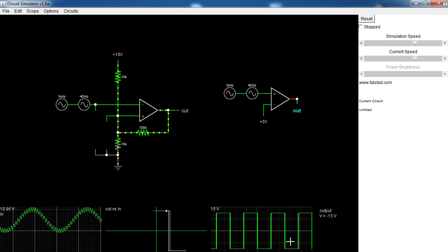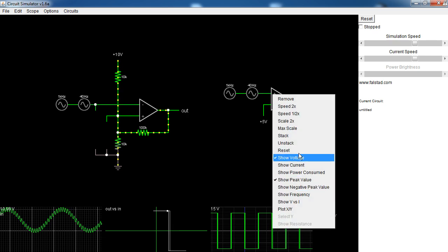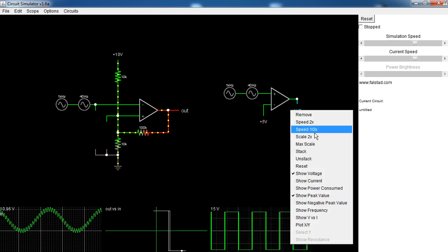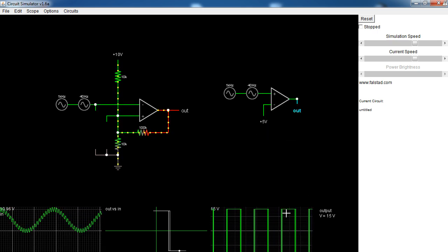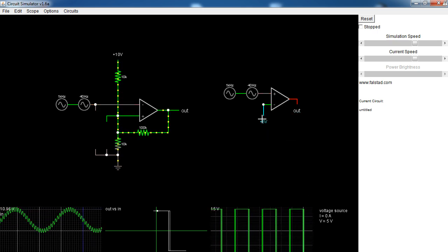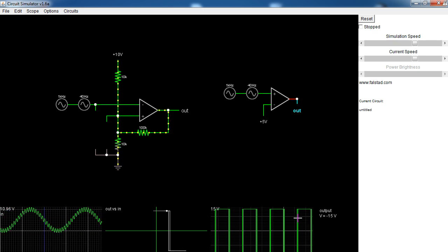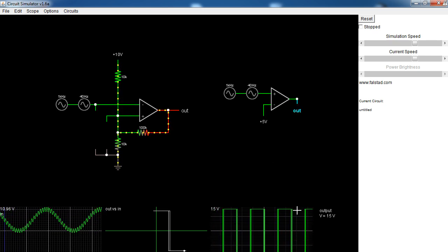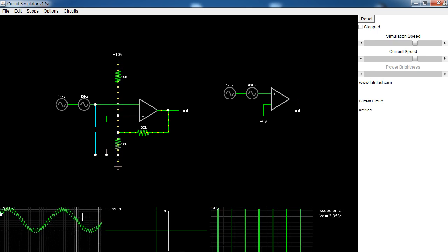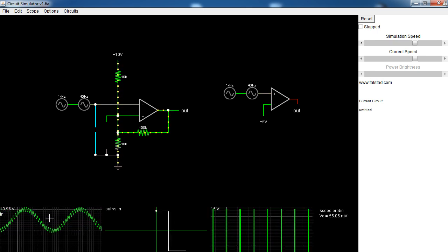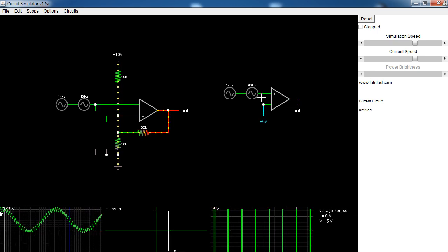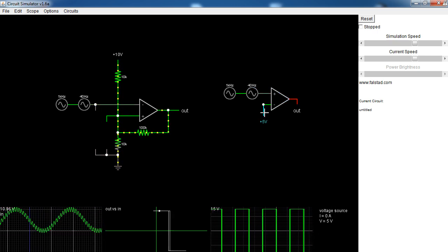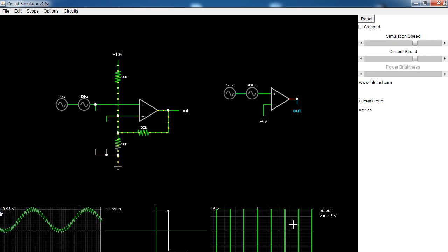As you can see in the comparator output, very good, zoom in, or I try to zoom in, you can see that on the edges of where it changes state, of where it goes below 5 volts, there's a spike up and down because of this jitter here. Because it's moving within a very fine band. It's moving quickly above and then back below the 5 volt line, and that's creating this jitter here.